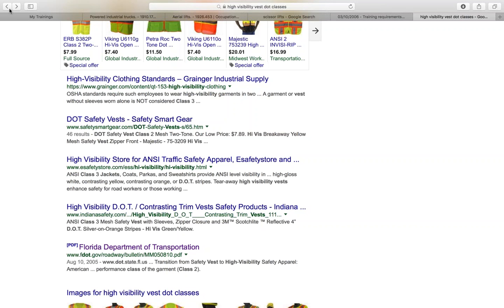If you look at the bottom of the page, you'll also see you got some misters there to reduce dust. Okay, just different tools and equipment that's available in the market. Also, all types of motorized equipment, right? Use fuels like gasoline, LP gas, right? Liquid propane gas, could be diesel fuels. So, any of these could also cause a fire. Battery operated, really doesn't matter. So we need to make sure that we keep our risk of LEL, our explosivity or flammability rates, down.